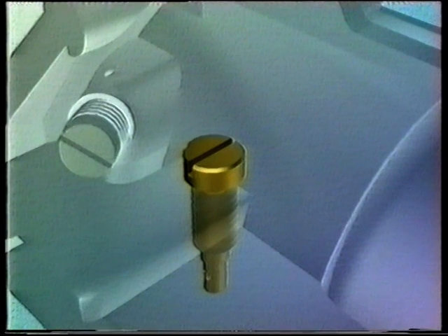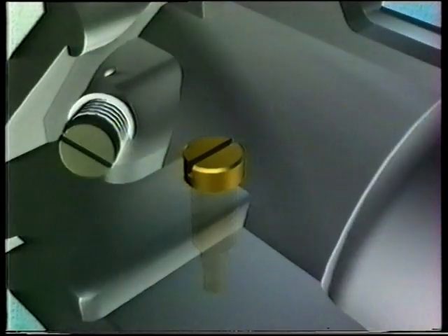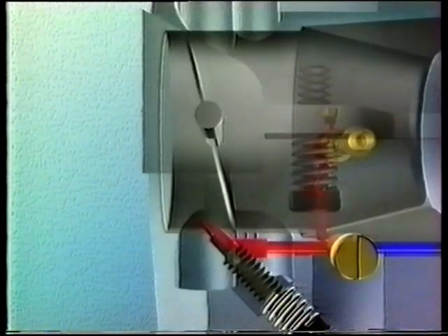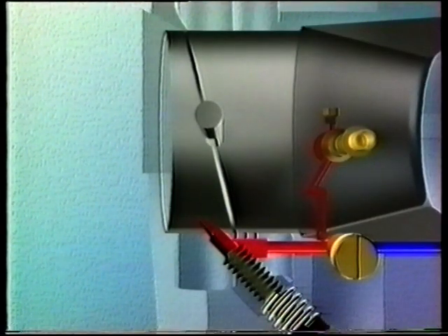Now, let's take a look at another aspect of today's modern carburetors. In systems which still feature an idle circuit, you'll often find a pilot jet, a fixed jet for the fuel introduced into the idle circuit and into the transitional hole reservoir.